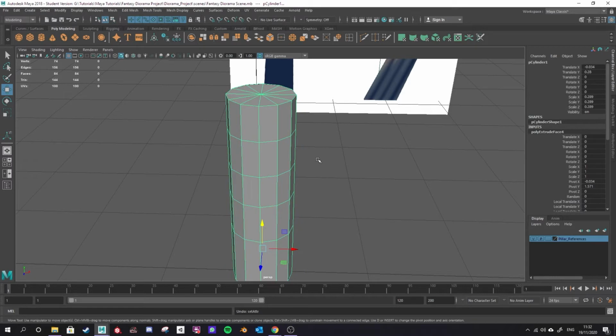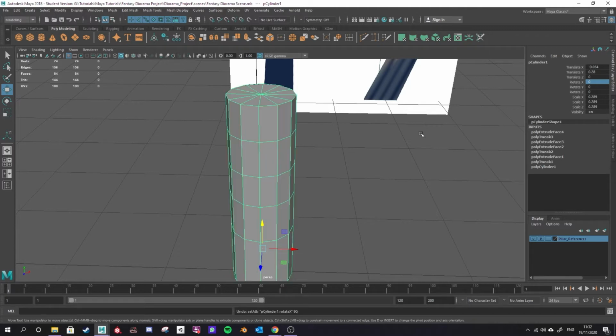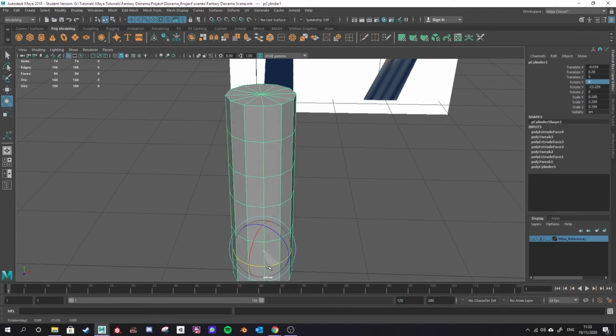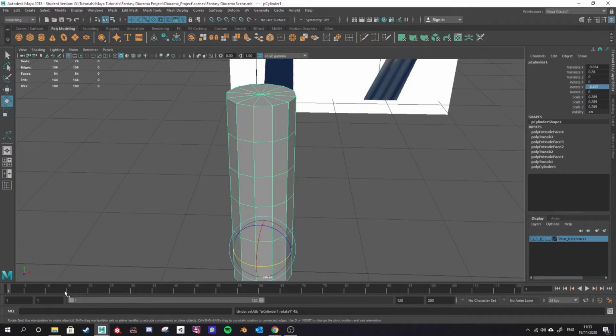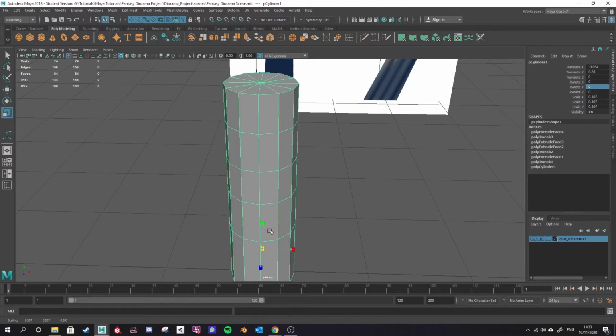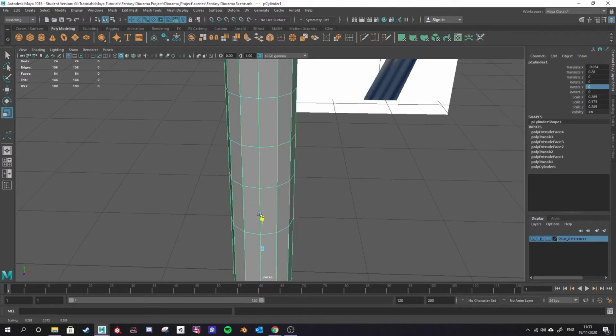So let's select my entire object there, and you see I can rotate the entire object just by using the numbers available to me there. You'll also see then if you're rotating something, for example, using the gizmos, as that rotates you'll see the figure changing on the right hand side, so you know there it's the y-axis I'm rotating on. So if you need an exact rotation, you can go up here and you can type it in to that axis. Sometimes it's hard to tell the axis just by looking at the little axis icon in the left hand side, so you can always tell on the go by scaling or moving, and you can see which axis that is moving on the right hand side there.